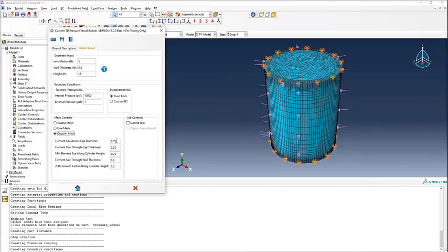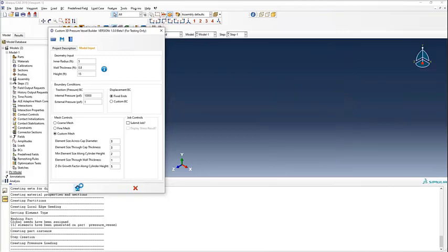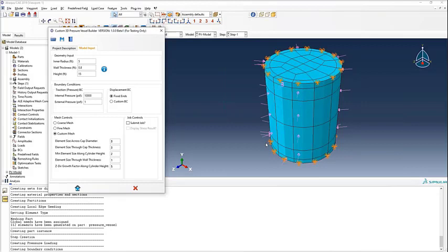Here we're going to specify actually larger values so that we can submit the job and take a look at the job control portion of the GUI. So we're going to just specify larger values for some of the seeding. And then the growth factor we're going to make pretty large along the length of the height of the cylinder. And you notice that with the custom mesh, as you press that radio button and move away to the coarse, it will actually resize and remove those extra text fields.